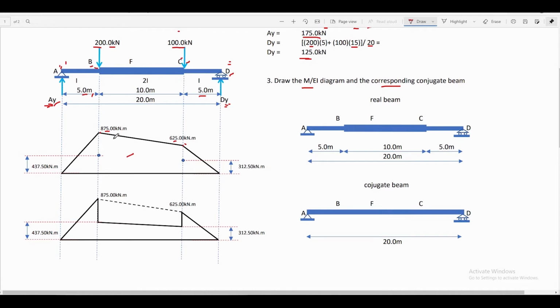We cannot apply this technique if the load is uniformly distributed, since if the load from point B up to point C is a uniformly distributed load, we will have a second degree curve from point B up to point C. And solving for the properties of the area under a second degree curve in this situation would be more tedious and complicated, since we have no direct formula to solve for the properties of that area other than integration.